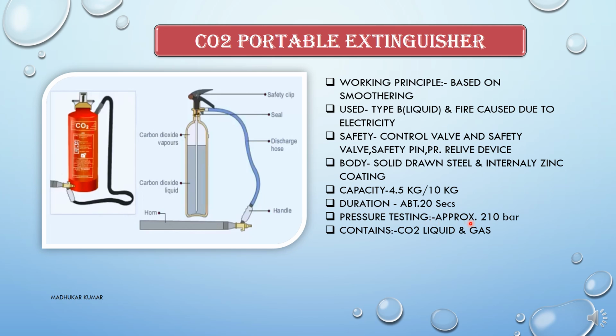Pressure testing approximately 210 bar, but it changes from manufacturer to manufacturer. It can be 225, 230, 235 also, depending upon that. You have to check on the label. And it contains CO2 liquid and gas both. So this is the description of the CO2 portable extinguisher.